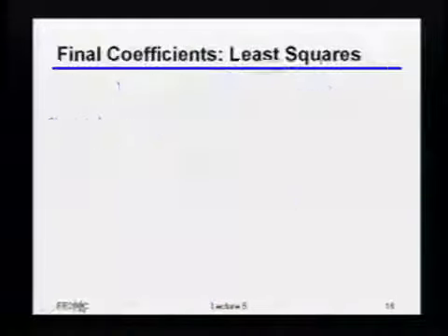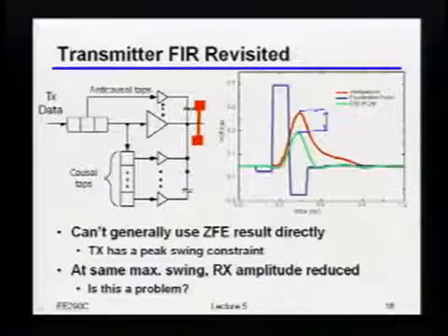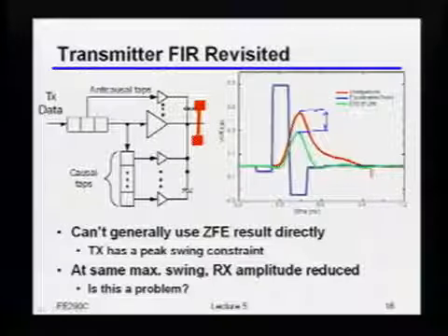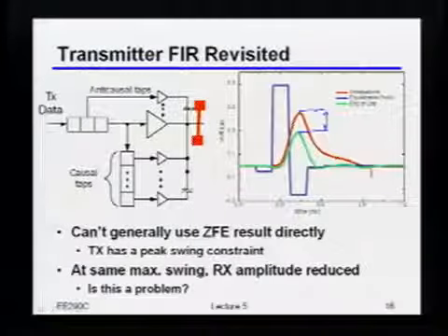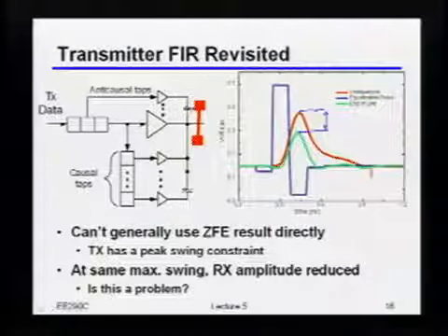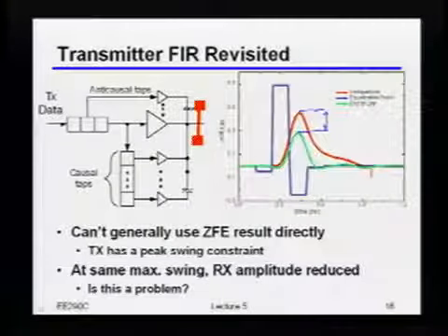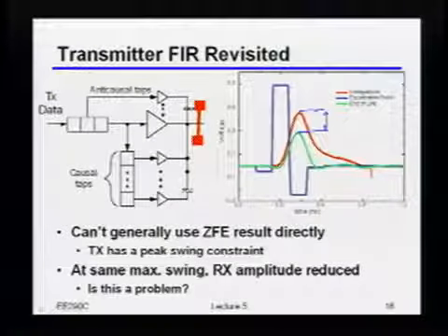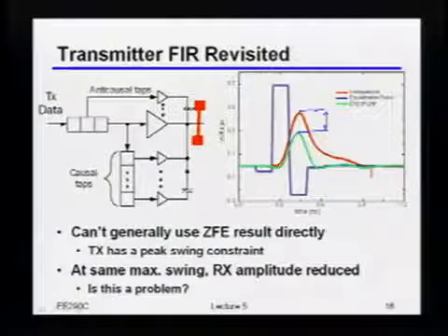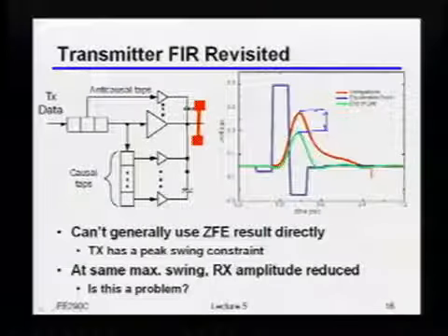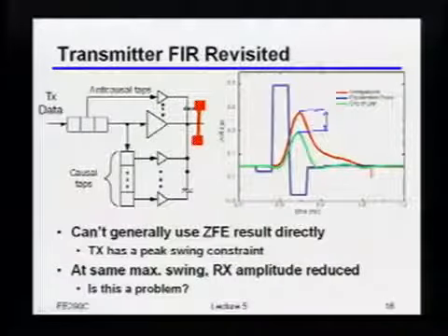And actually, I guess this one shows it too. So if you've got a dispersive channel, you tend to have a lot of junk right next to you. Right? And in particular, that first post cursor tends to be pretty darn big. So a lot of times, if you did that, you kind of lost a lot of the advantage of doing the DFE in the first place. So if you looked maybe about 5 to 7 years ago, you would see a lot of these solutions that had so-called gaps in the equalizer space, where the DFE just couldn't actually cover it.